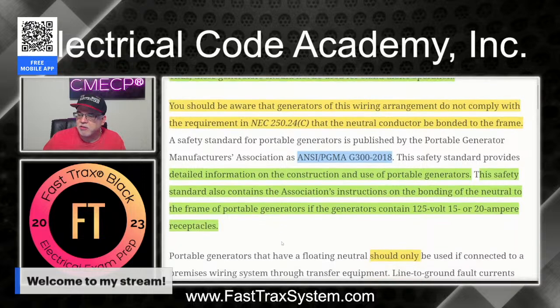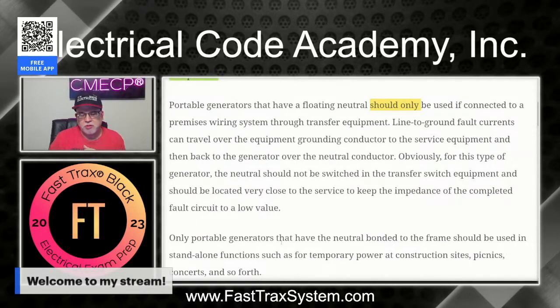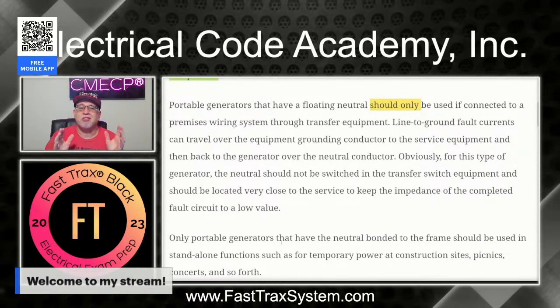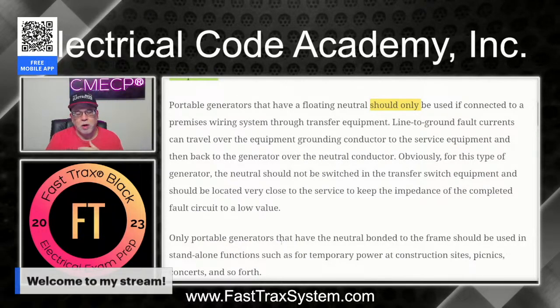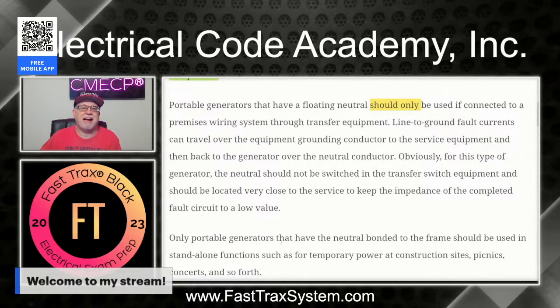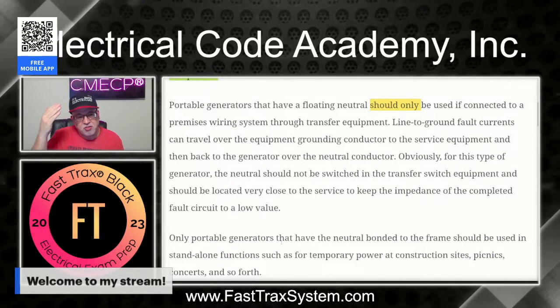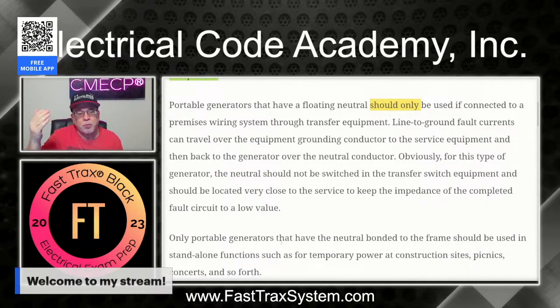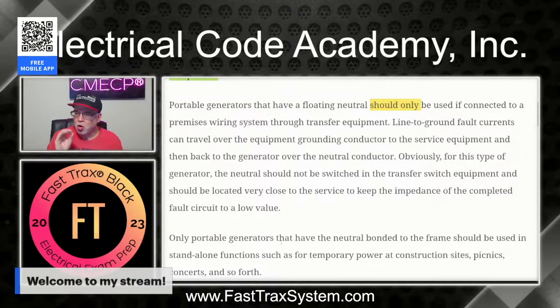Now, when it comes to generators, the only other thing I can tell you is you have to be careful because there's a lot of makes of generators, and not all generator manufacturers understand the difference and the importance of what they're selling their generator for. Most of the portable generators that you would see out there, you'd have to think they're being used in a portable application as a standalone, as a separately derived type system, right? And so if that's the case, we want to make sure we have that system bonding jumper in there, or that connection from the neutral point over to the frame. Okay? We want to make sure that takes place in those type of systems. But you got to be careful what you buy, okay? So you know what you're getting.